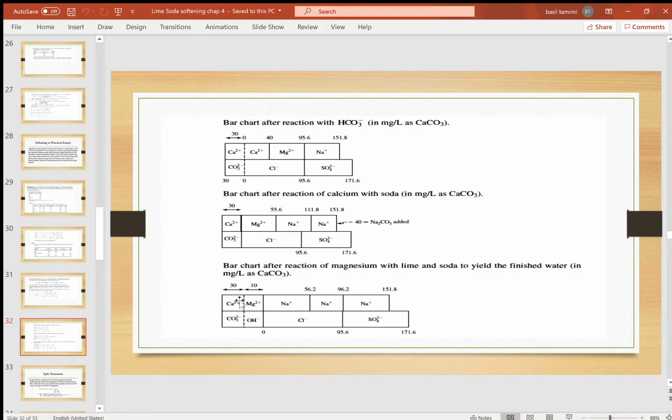This was decided based on the fact that calcium is a predominant element. Usually calcium is present in water with higher concentrations than magnesium. And also, taking an average, it is maybe 3 to 1. So they said, okay, if we have both of them present simultaneously in water, we can say this total 40, 30 is for calcium because it's the predominant, and 10 as, of course, milligram per liter as CaCO3, is for magnesium. Okay, so this is completely correct.